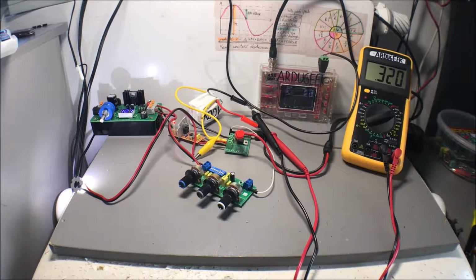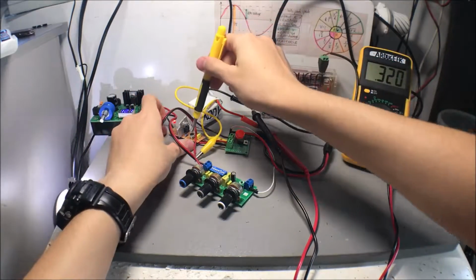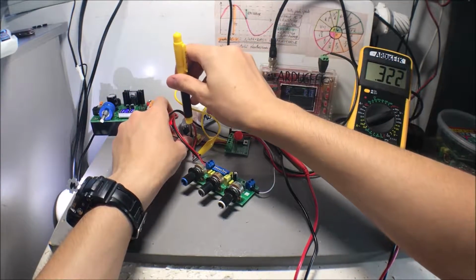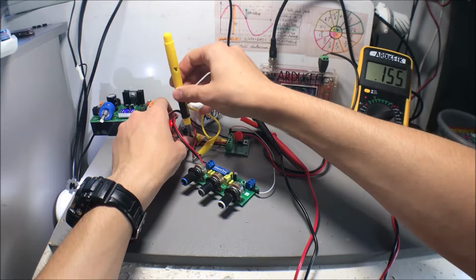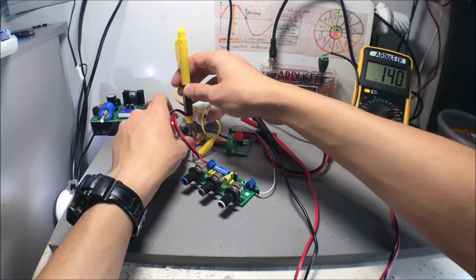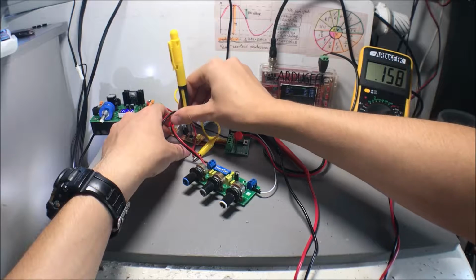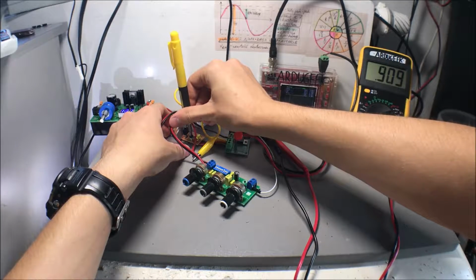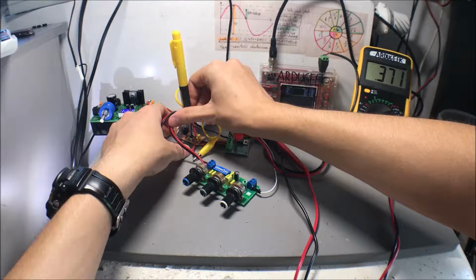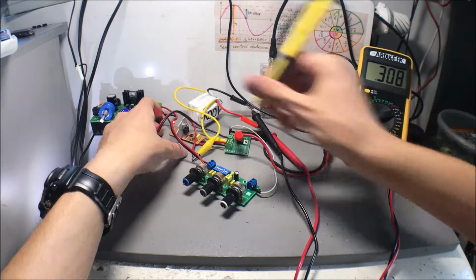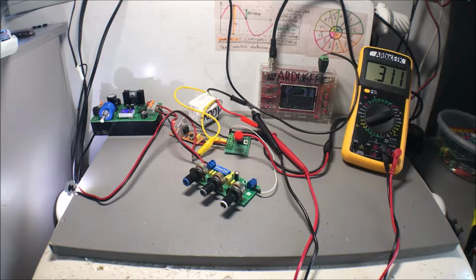Of course, if I get my screwdriver in a moment, I can lower this current. It dims the LED a bit, and the minimal current in this case is 140 milliamps. But the best amount of current to not blow up our LED is the recommended 320 milliamps. So that's why I'm limiting the current, because I don't want to burn the LED, and mainly that's the whole purpose.